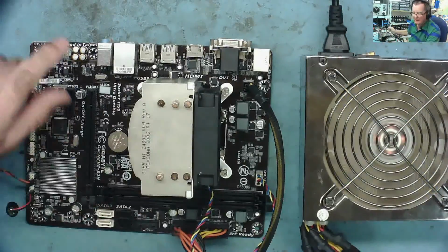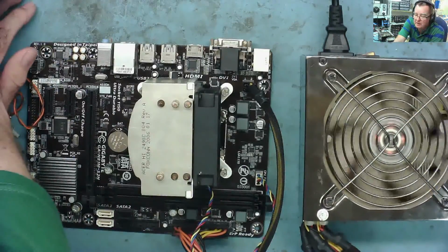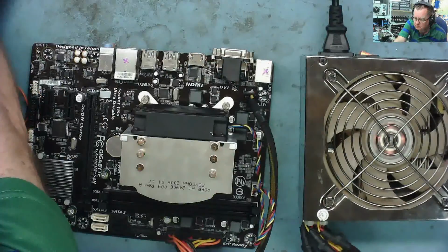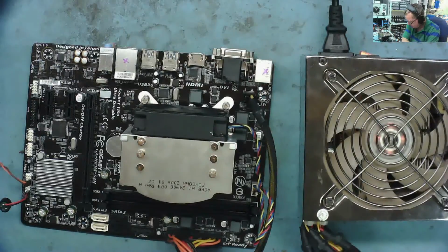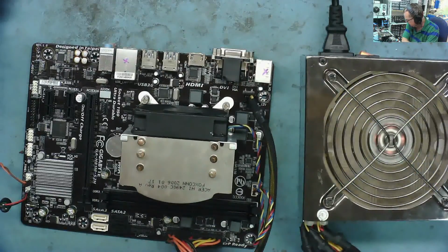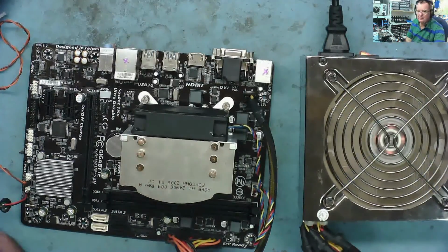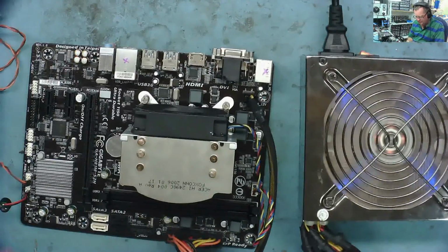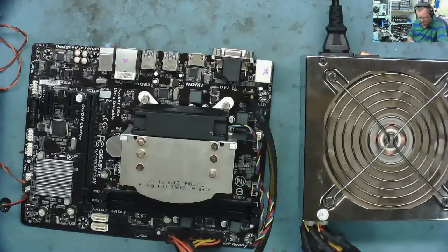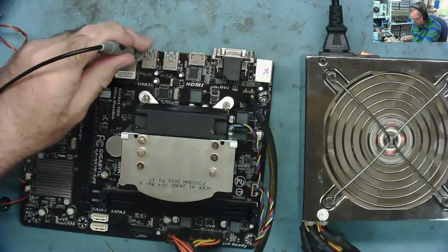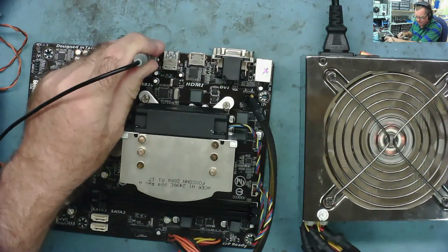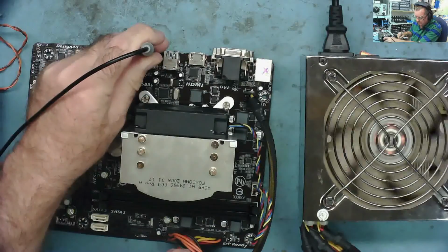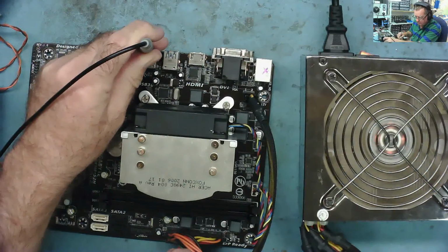Okay, let's do the same with our board now. So no RAM with the 12 volts connected. Right, so this is exactly the same as the other one. No RAM, 12 volts connected. Powers on, powers off. Now, that I can accept it doing, because there's something wrong with it. And if we measure like we did before, from ground to the green wire, this is going to 5 volts then to ground.